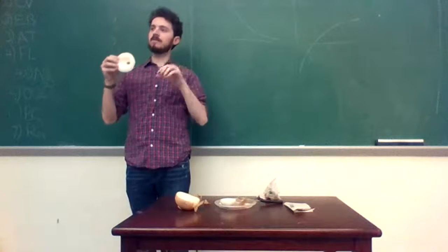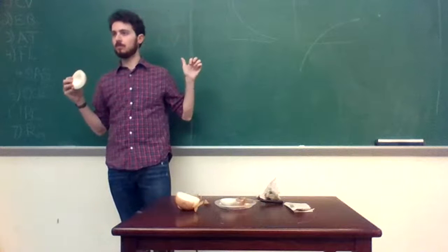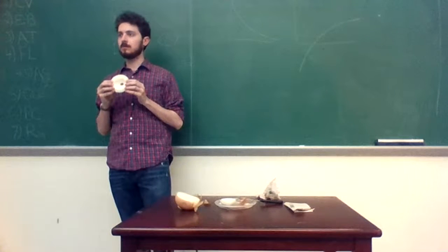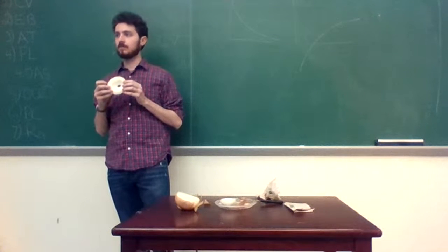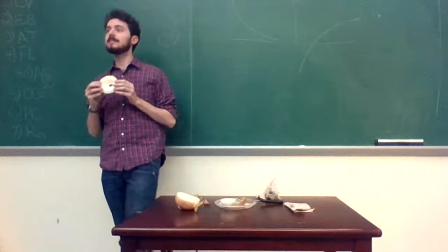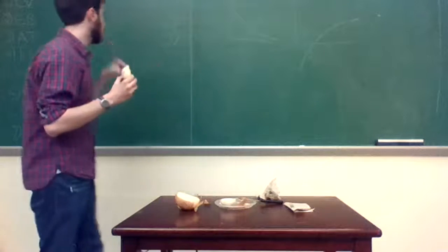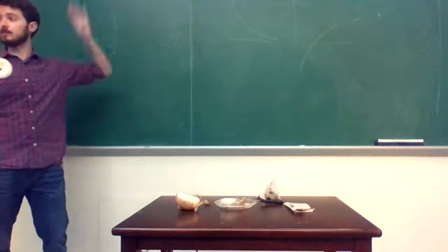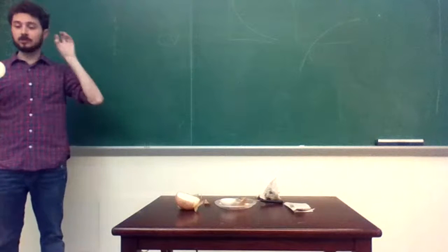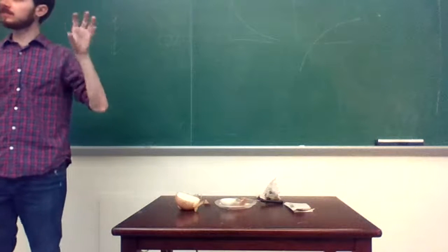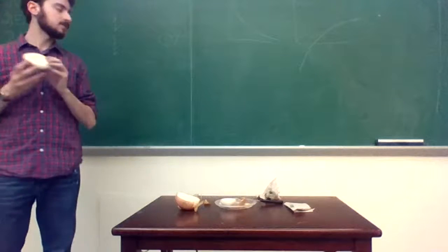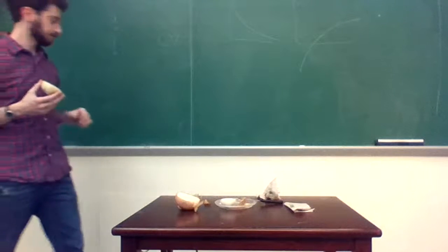Through each layer of this onion, what is your Q? What's your heat rate? Yeah, it's always the same. That's the critical thing, is your Q, assuming no internal heat generation, we're stepping away from internal heat generation. When you've just got that shell resistor type of problem, Q is always going to be the same.